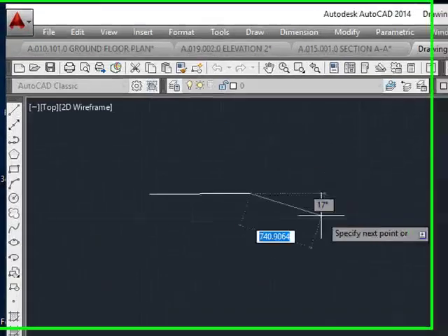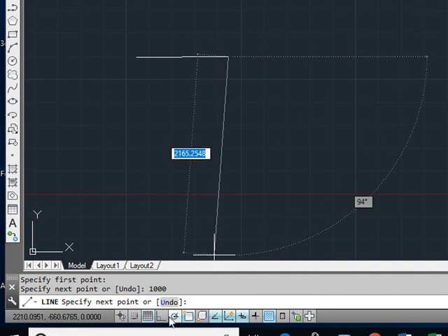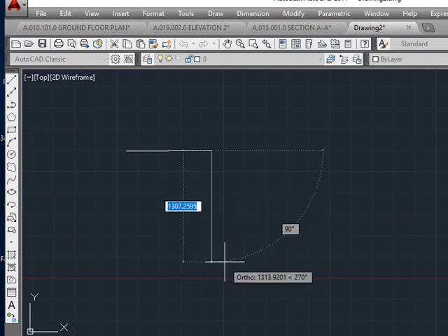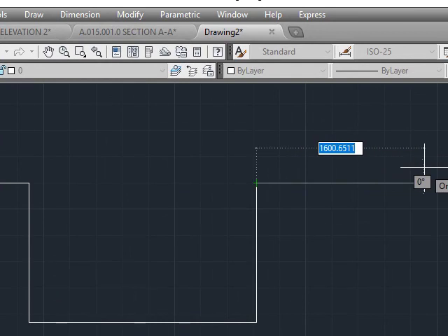The direction of the lines can be anything, freely. But if you want to make a line directly without any bending, you have to come here. We have an auto mode, written F8, or you can directly type F8 from your keyboard. Then your line will be direct. I mean, it will be at a direct angle, 90 or 0, like here, like here, like here. There will not be any bending or any other thing.